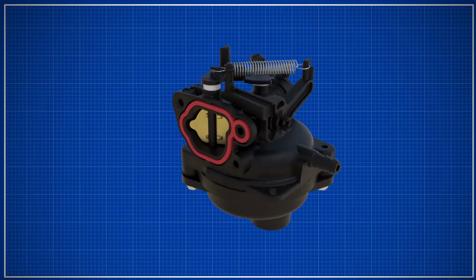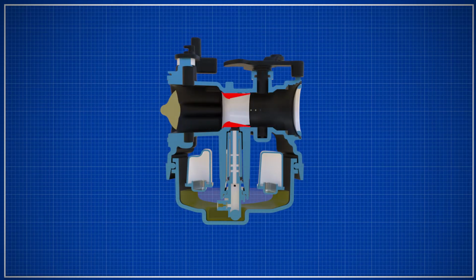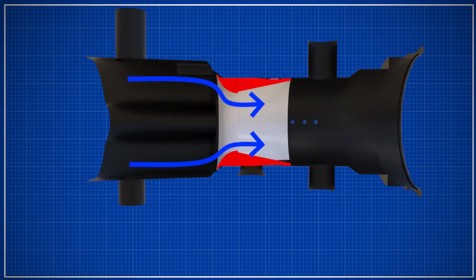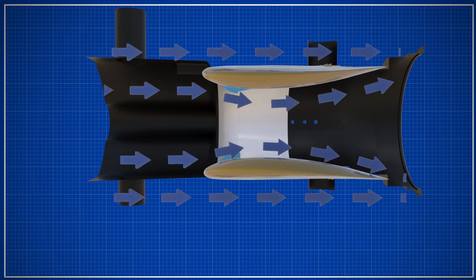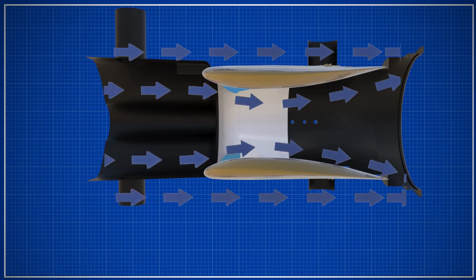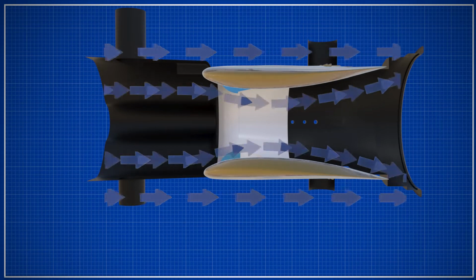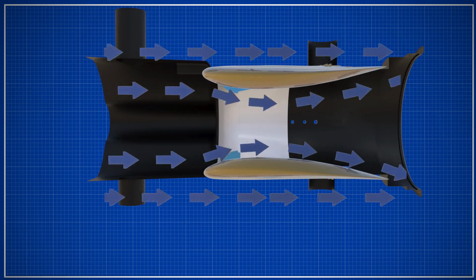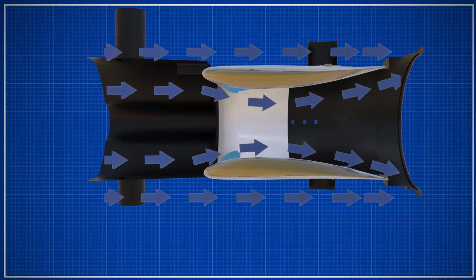How is an aircraft wing related to a carburetor? In the carburetor body, there is a passageway that narrows from one end to the other. This feature is known as a venturi. If you compare a cross-section view of an aircraft wing and a carburetor venturi, you will notice the two are almost the same. The venturi is built the same as a wing on the top and the bottom that makes a narrow passage for airflow.